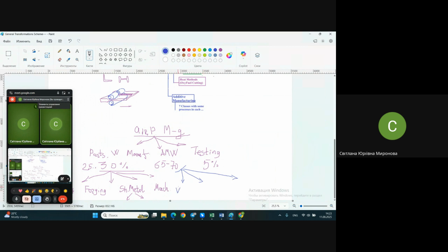So we have wing assembly shop, fuselage assembly shop. The truth is that usually the fuselage assembly shop is not the only one. We have, for instance, nose fuselage shop, central fuselage shop, and aft fuselage shop. For the wing, usually it's enough to have one shop. And we have maybe what is called tail unit or empennage shop, shop of high lift devices or flight controls. For instance, let it be empennage shop here. Let it be an additional shop of flight controls.